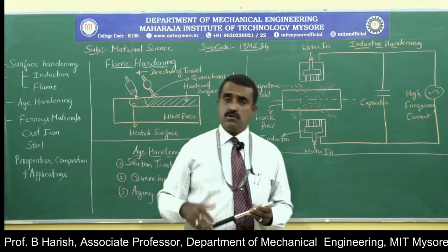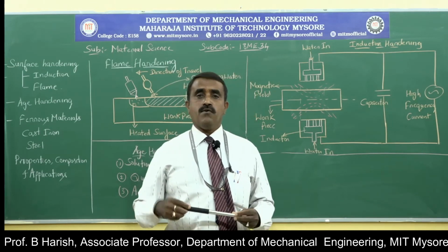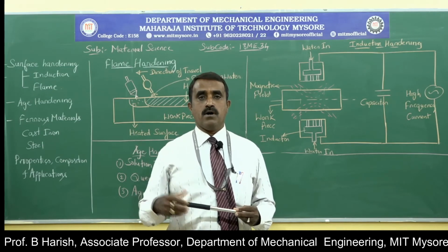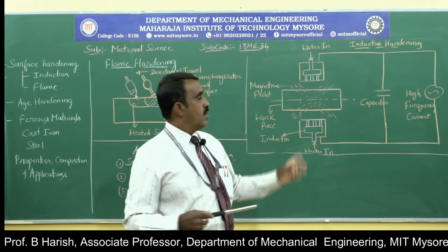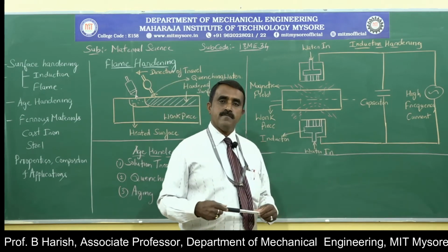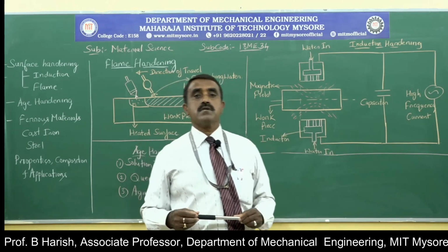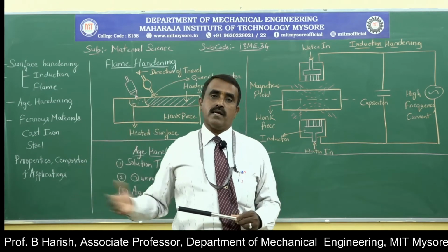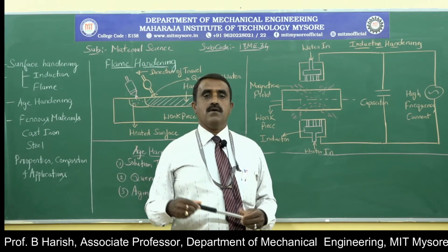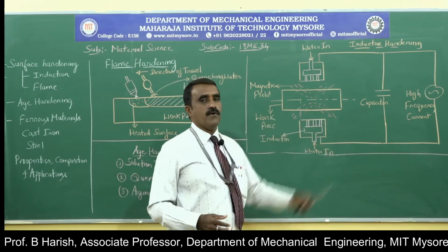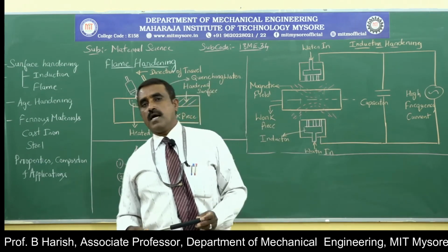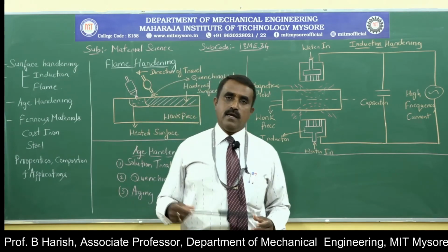This was one of the objectives of surface hardening or surface heat treatment, discussed in the previous session. So a very good surface finish can be achieved. Second, the heating process is faster when compared to flame hardening. So that's about the second type of surface heat treatment, called induction hardening.